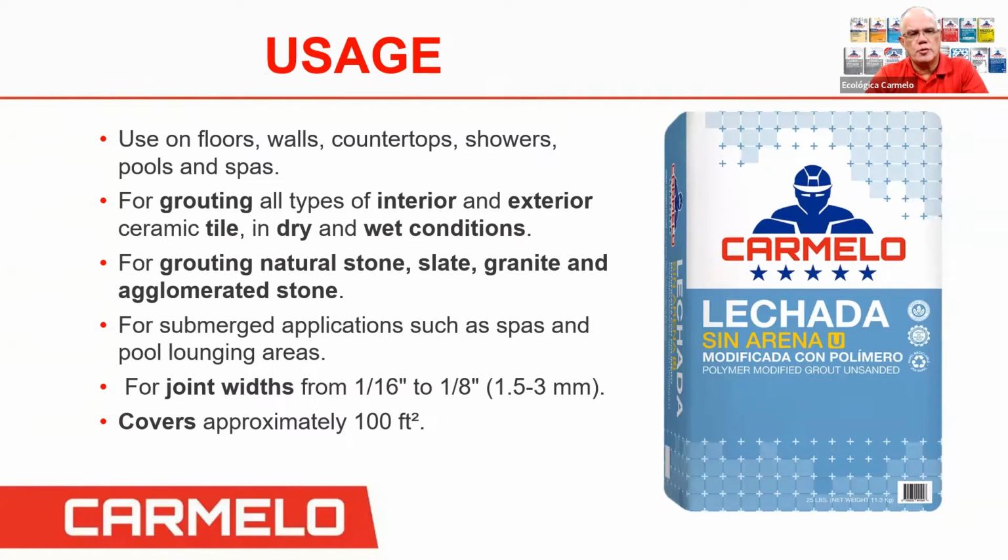And also your unsanded, you would use it where you have joints from 1/16 up to 1/8 of an inch, right? And they cover about 100 square feet.